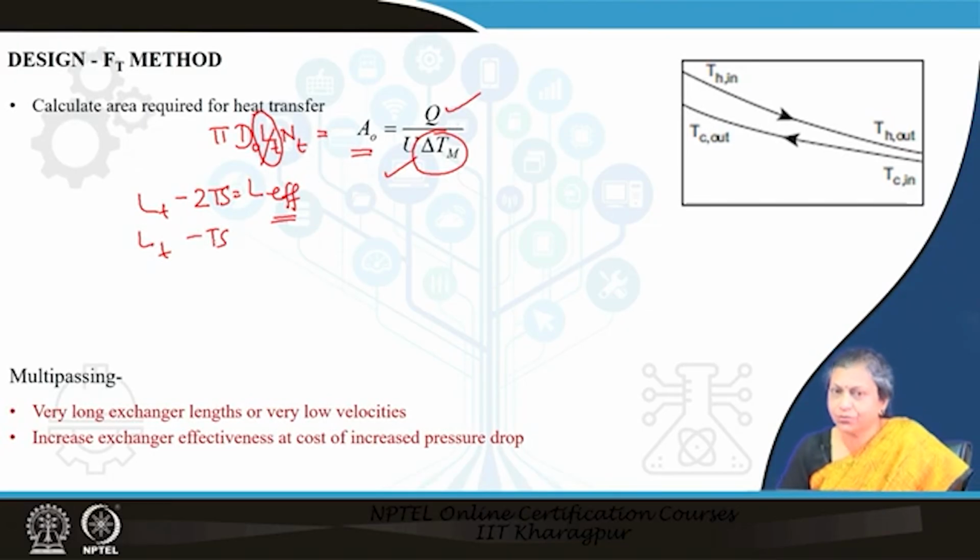But again, you have to remember something which also has to be considered when we decide on the effective length, because it is not just the length which is inside the tube sheet, but there are also certain other areas which are not available for heat transfer. I leave it to you to think about it. In a while, I will be discussing a little about the L effective, right.